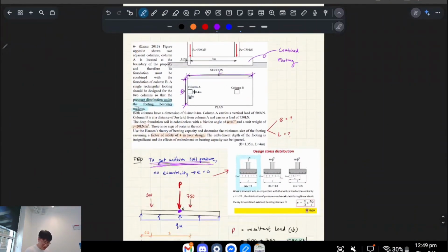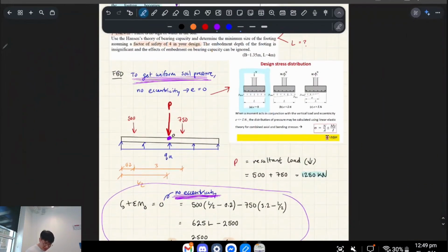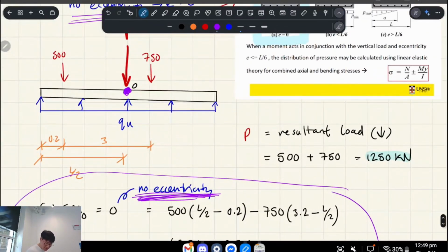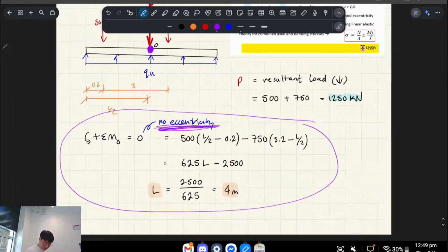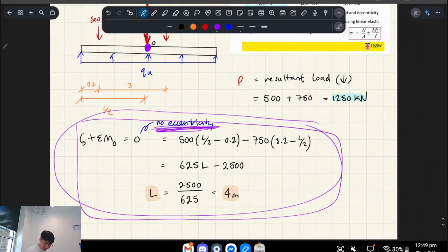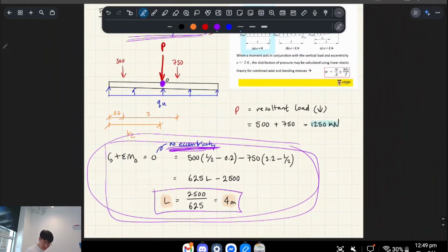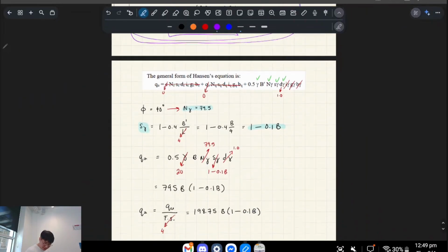Oh yeah, sorry. Well, I remember what the question was trying to say. It's trying to say, what is the optimal length and width such that there's no eccentric loading, right? So there's no eccentric loading. So the middle is where the equivalent force goes down, right? And you're taking the sum of the moments, right? And that's how you work out algebraically that optimal length, right? And then